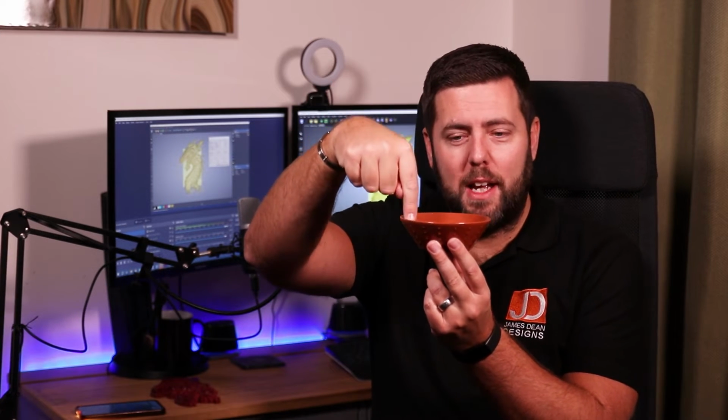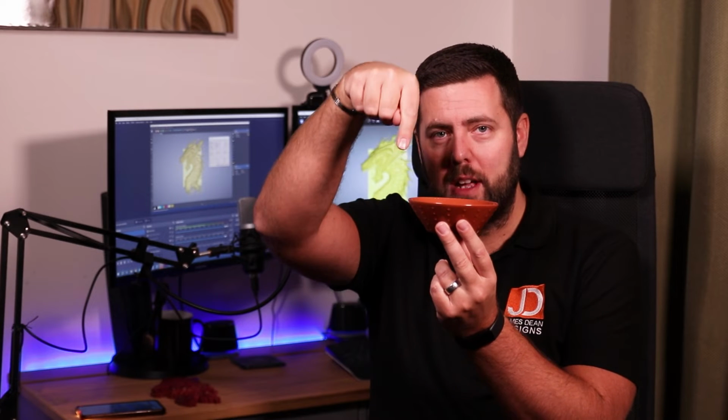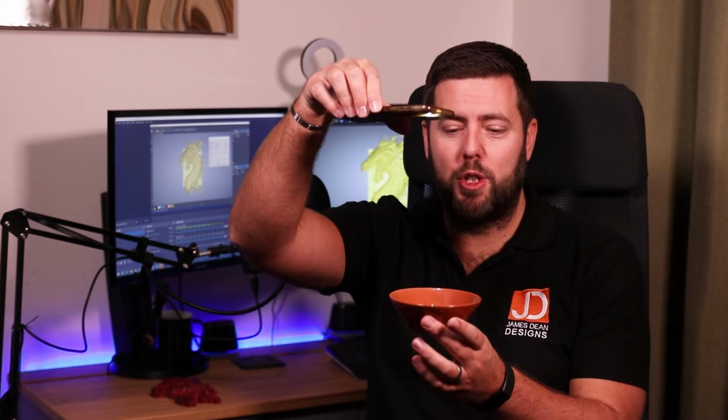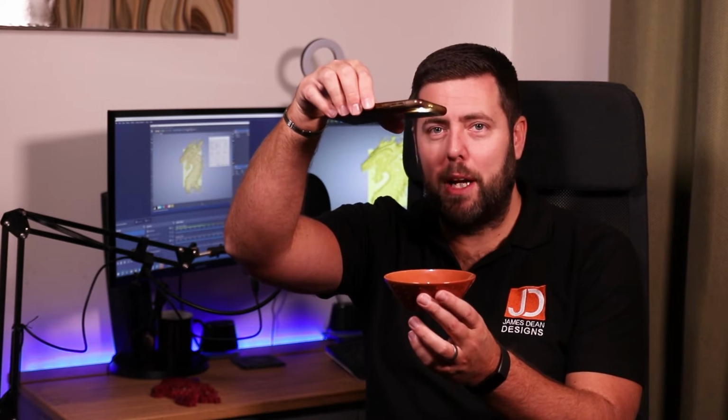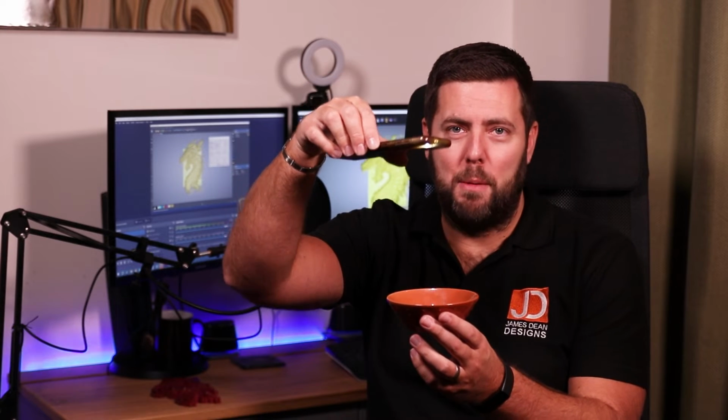So it can come down, it can machine all the middle of this bowl out, but it can only go down the side. Now the way this is handled is effectively anything that becomes underneath and shadowed gets blocked in, and it just fills it all in to make it a solid model. The easiest way to think about this is if you imagine a light or torch shining down on top of it, everything that becomes in a shadow is going to get blocked in.